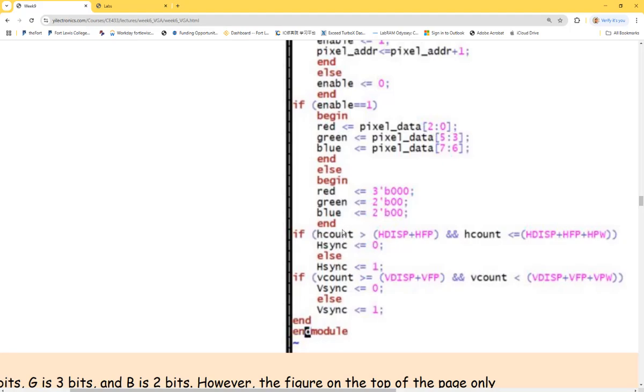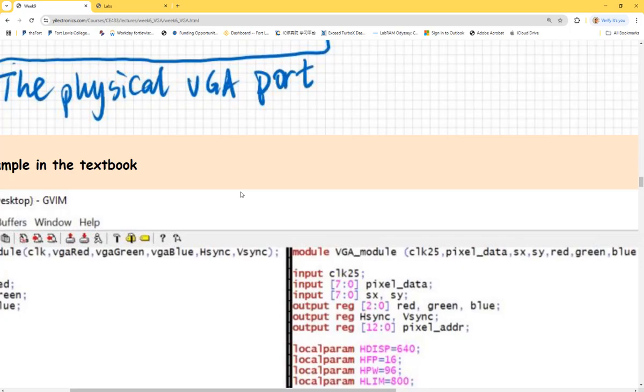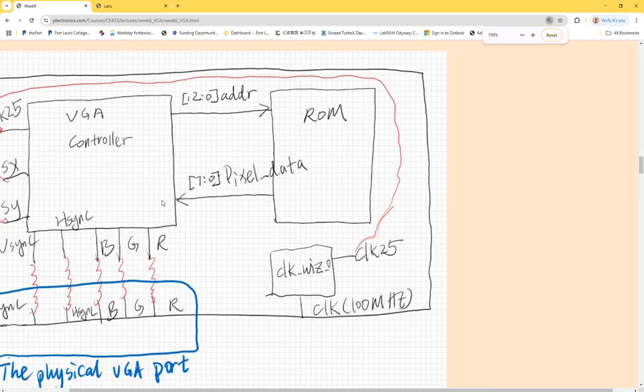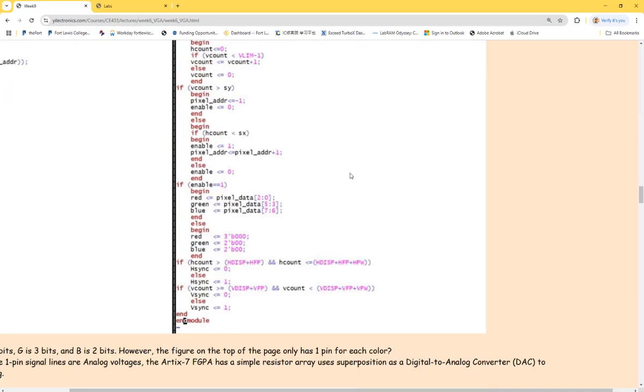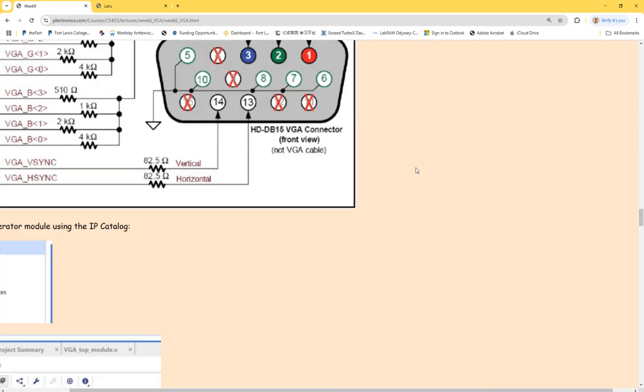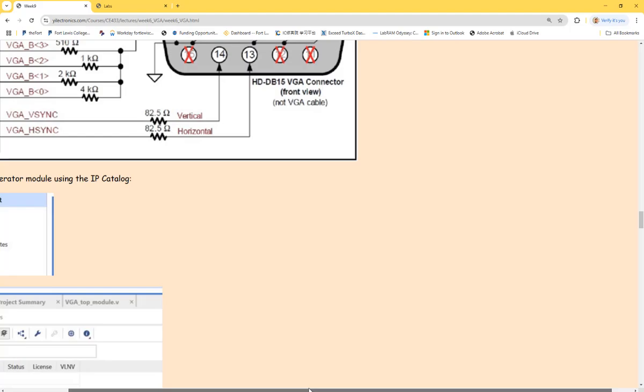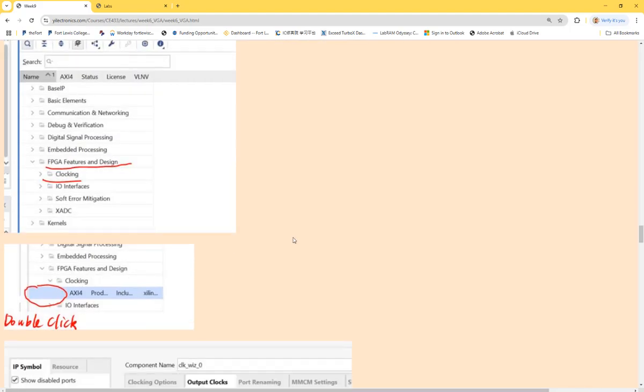So these two are very standard. You never need to change this at all. So the bottom two if statements are not changing at all. These are all the counts within that sync's range, which is over here within this range. Okay, then just to give a sync signal. That's it. Very simple. So I think for this tutorial of VGA, the lecture is very straightforward.